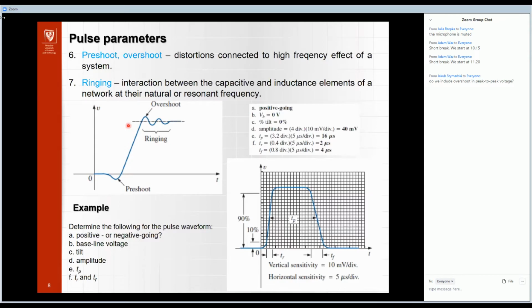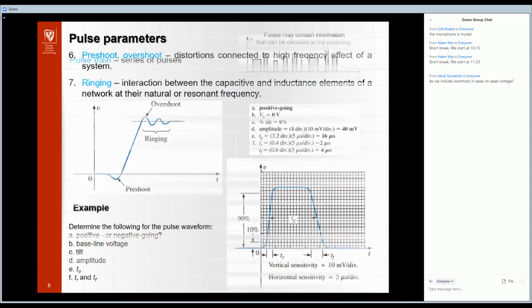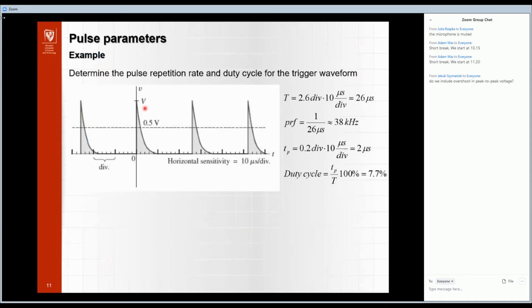Of course, we also have the offset regulation in the scope, but sometimes it is not enough because the signal is too high. For example, when we want to observe this noise, it is not possible without using AC. But when I cancel the average value, I can observe only this, and it is the reason why we use AC in the scope.